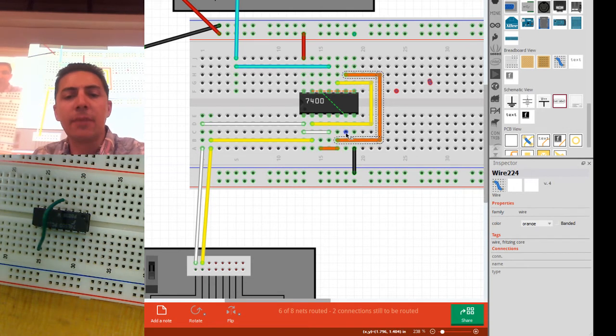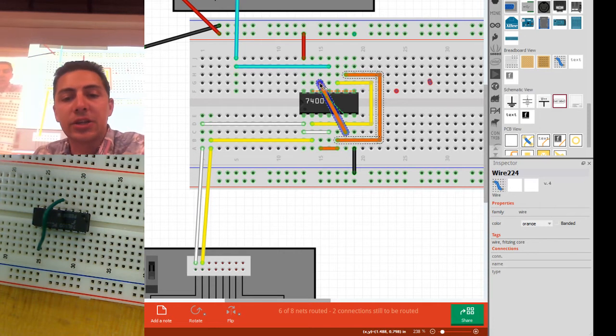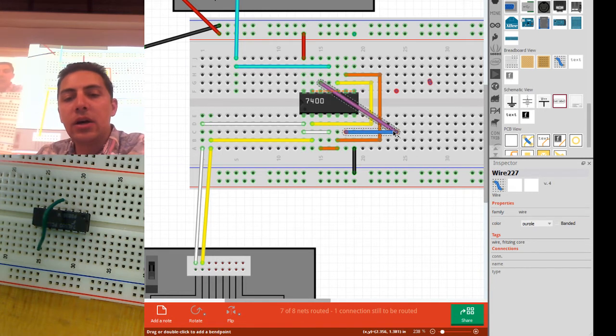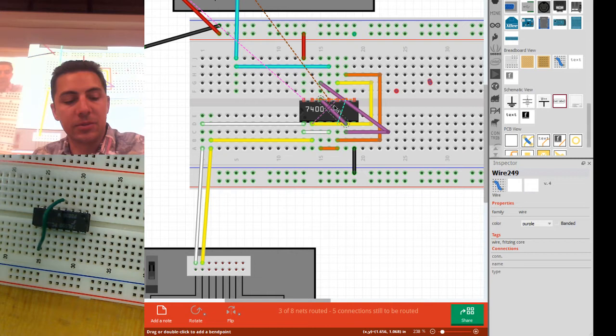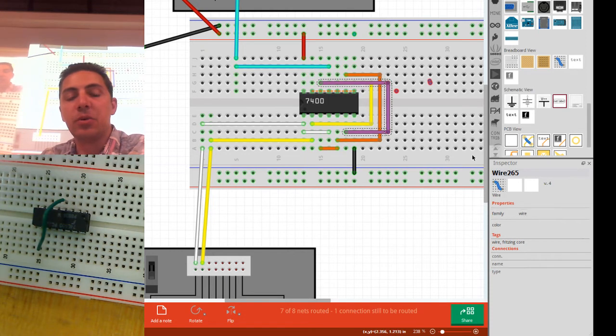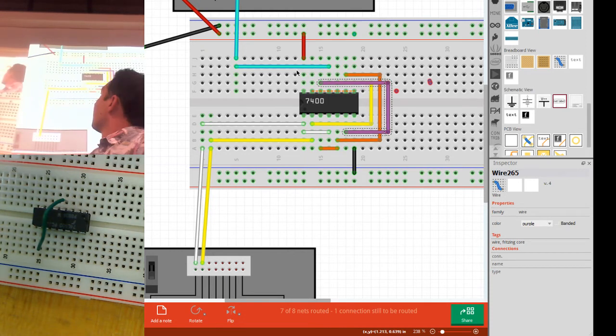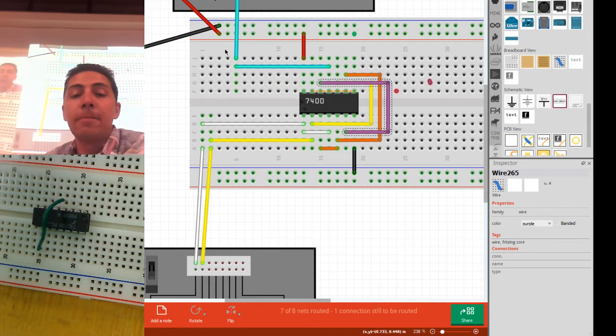What else do we need to do? That pin is connected. I'm just going along and clicking on everything and seeing if there's a wire to it. Here, we've got to make a connection. And I'll make this one pink. I like pink. Or purple. I'll do purple. All right, so now this is the real advantage of previs. We want this to go... Oh, let's not do that. It is possible to accidentally pick up the chip. You just want to make sure you place it back in the same place. It is possible now to put this purple wire in, but a bunch of problems have just appeared. Purple is now covering that yellow wire. It's crossing over the orange wire.